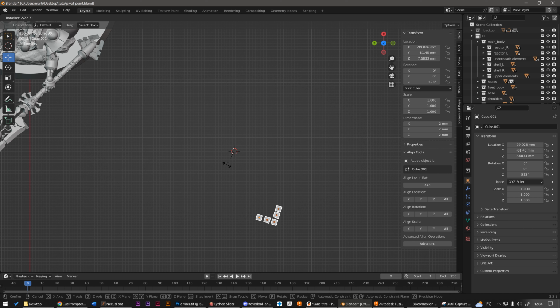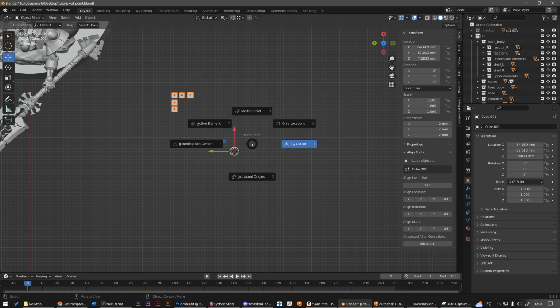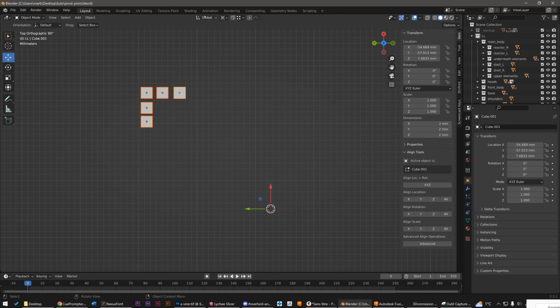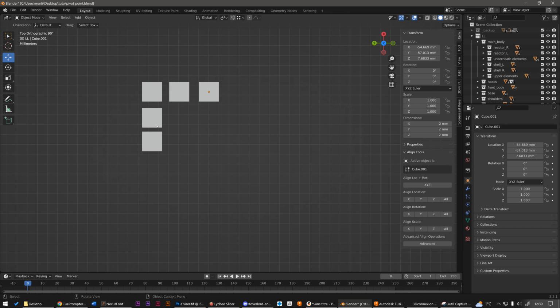And if we activate the Only Location option, we will be able to use the rotation tool only for the purpose of a circular translation, so there will be no rotation. And that gives us this. We can clearly see that objects are moving on the circular path, but their orientation remains at 0. With this mode, we can animate objects in a, let's say, magic way, because we're not used to seeing objects rotating like that.